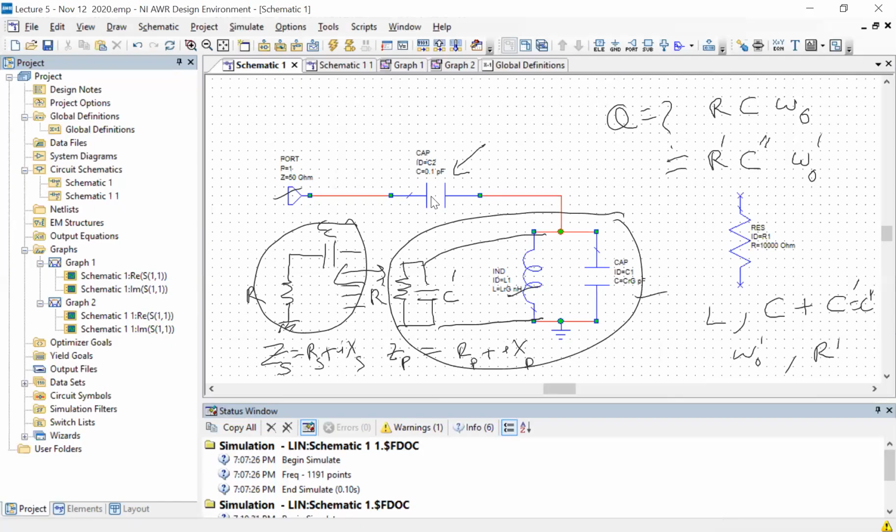What is the underlying assumption for this equivalent circuit to be valid? These are all impedances, right? Are they constant? No, they can't be constant because XP will be omega dependent. Exactly, XP or XS, whatever.